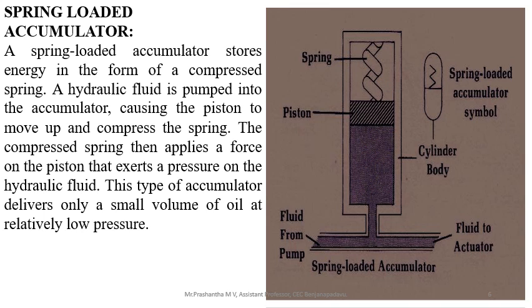When we go for operation, as the fluid enters the accumulator, the spring is compressed by the hydraulic fluid. The pressure in the accumulator depends on the size of the cylinder and preloading of the spring. In the accumulator, oil pressure increases as the spring gets compressed. When the fluid is discharged from the accumulator, it causes the spring to expand. As the spring approaches its free length, the accumulator pressure drops to a minimum.